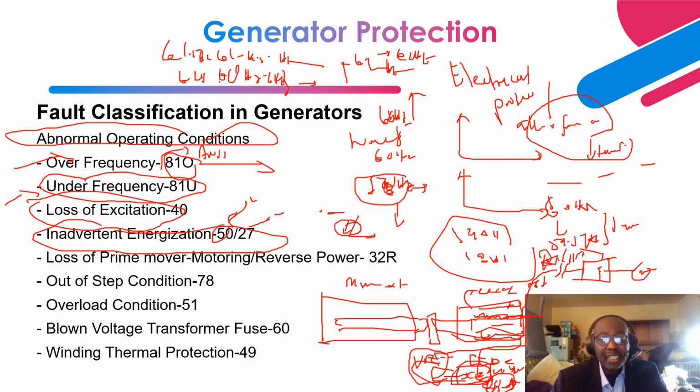It has an embedded heat, and that embedded heat takes time to dissipate because of the time constant. To prevent bowing of the turbine generator rotor shaft, it is put on a turning gear.